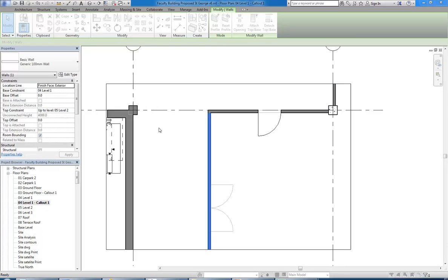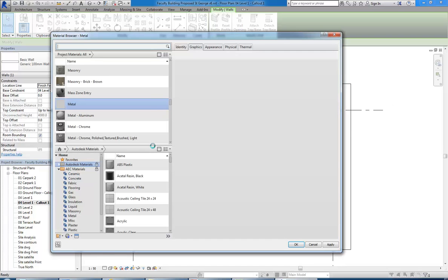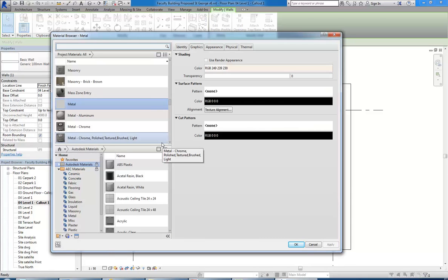And you'll see this quite often when you first open up materials in Revit. It might take a minute. Don't worry about that. It's just loading the rendering engine. It only happens the first time. And so you can, if you click on the button in the bottom left-hand corner there, set it back to by category, which is kind of the default option with Revit.